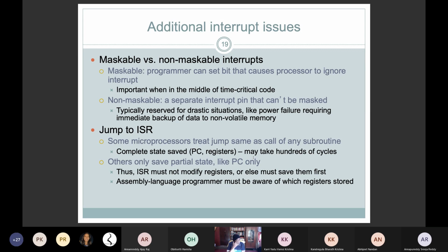There will be no garbage, because whenever there is a power out, garbage is possible. When the voltage is coming down, 4.5 volt, 4 volt, etc., the TTL logic or whatever logic you are using might confuse it with 1 or 0. So there may be garbage written. This brown-out detector is responsible for taking care of this garbage. Therefore it is non-maskable.